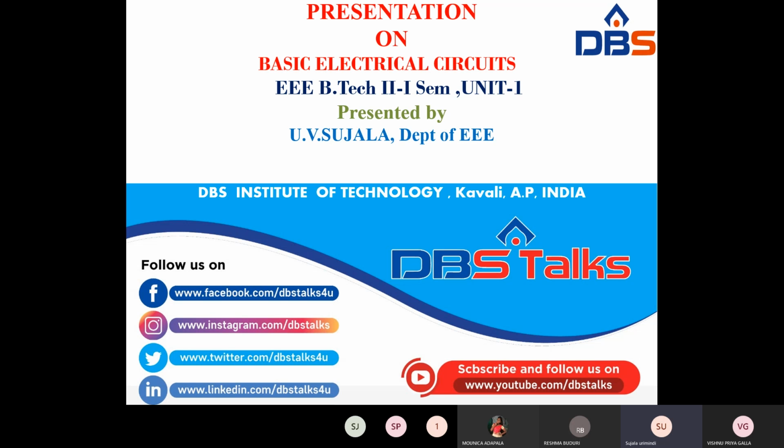And the third thing, you have to write down the equations. That is the KVL equation. How do you write down the KVL equation? The algebraic sum of the voltages is equal to 0. When there is a voltage source, we do not need to write it in the form of Ohm's law, I into R1. Only the voltage will be there, that is V1. When there is a rise of potential, put it as a positive sign. When there is minus to plus, put it as positive. When there is plus to minus, put it as negative.